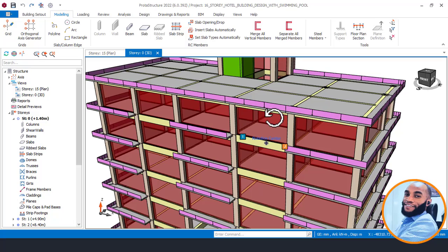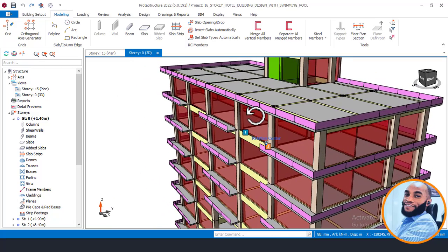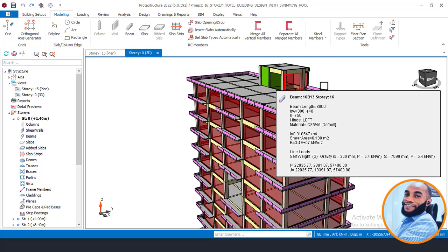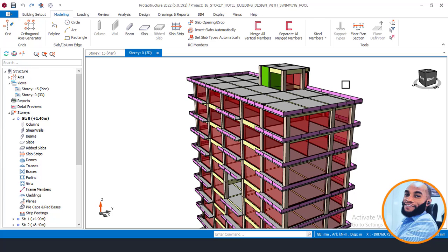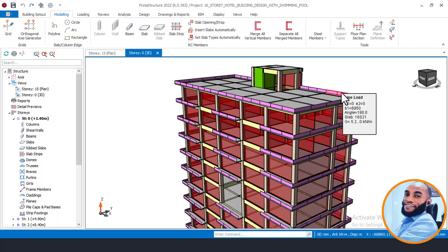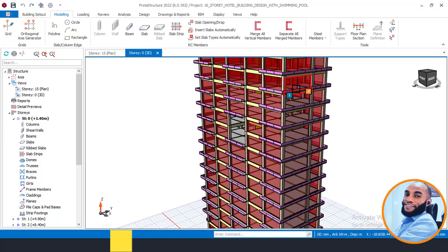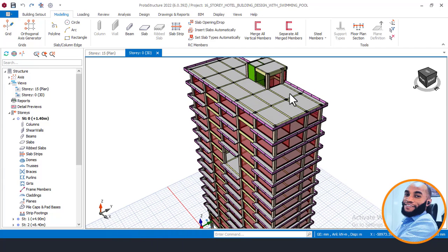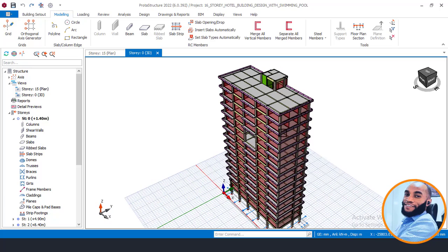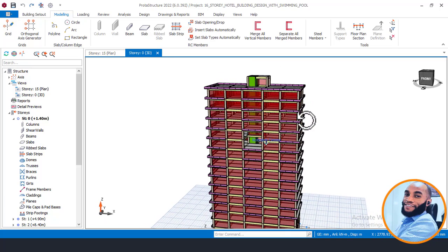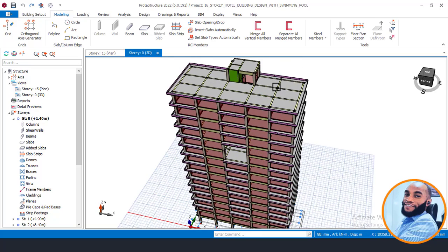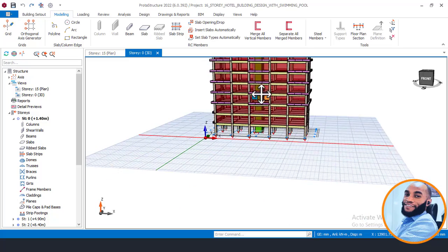Okay. Now waffle slab is a very good way for you to reduce load. I said before in our part A that I will show you two ways on how to reduce load. One is to apply waffle slab, and then the other is to reduce the load by the percentage of the stories. Okay. So right now, let's begin with the first one, which is to reduce the load based on the waffle slab. Now, the question that will come to your mind is, if I am to reduce my load based on waffle slabs, and knowing that I have solid slab right from the top floor here up to the last, which is this ground floor here.